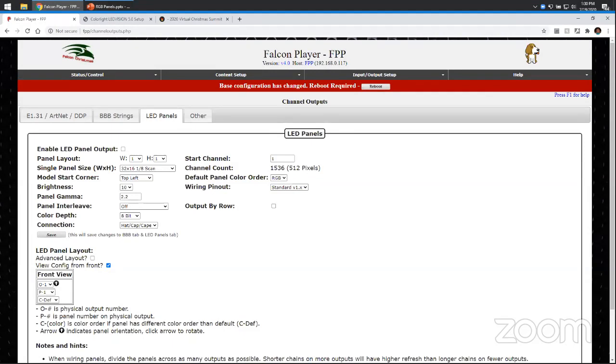How many panels can a Pi Zero control? I'm not sure, I can't remember. Pi Zero typically uses a bonnet that has just one output, but I believe it can control 12. But don't quote me on that. I don't know if Brian Rudy knows the answer to that. Maybe he put it later here. Go ahead. Yeah, I just wanted to say I wouldn't do any more than 6. That's pushing it already for a Pi Zero with P5s. The Pi Zero's got a much lesser processor than any of the other stuff out there. Pocket Scroller has 6 outputs. Thank you for the correction.